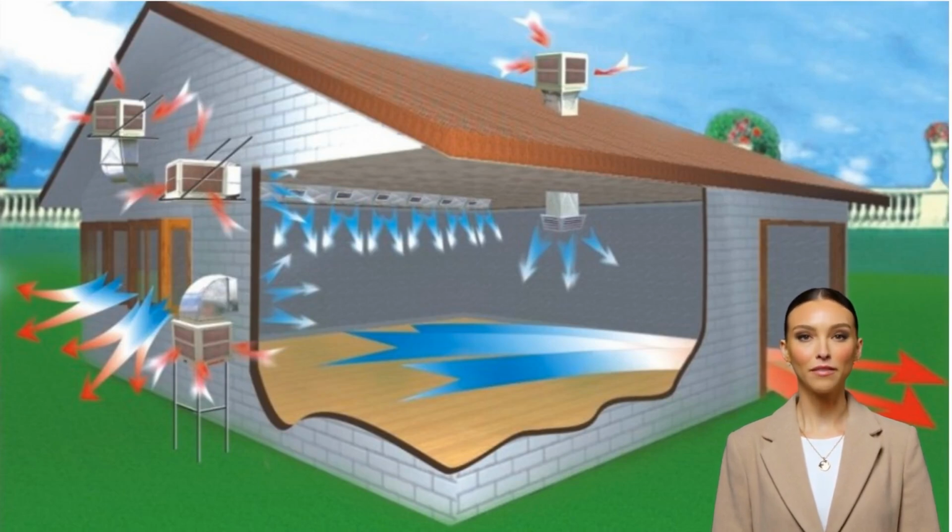On the ground. This is the simplest option in terms of installation and maintenance. It is recommended to use brackets that prevent dust from being drawn in from the ground and protect the unit from rain or snow. The second option is wall mounting. This setup saves space, but with side discharge, the unit's performance decreases by a quarter. The third option is roof installation. This is used for walkable roofs with safe and easy access.